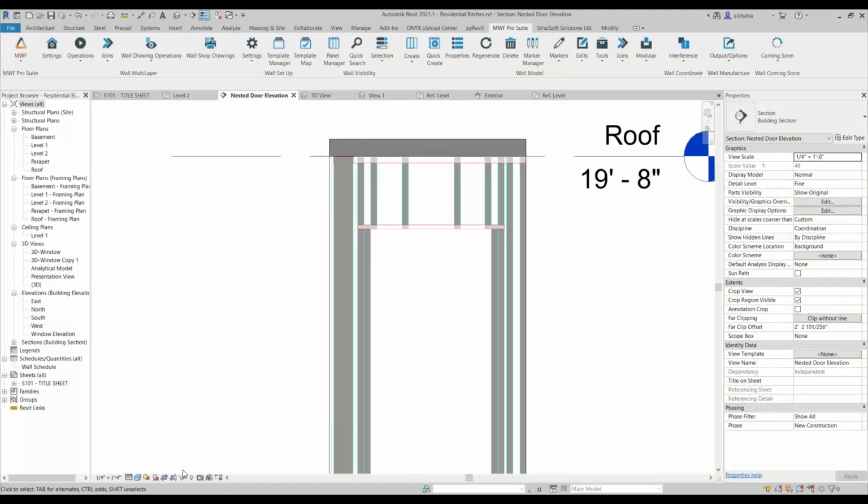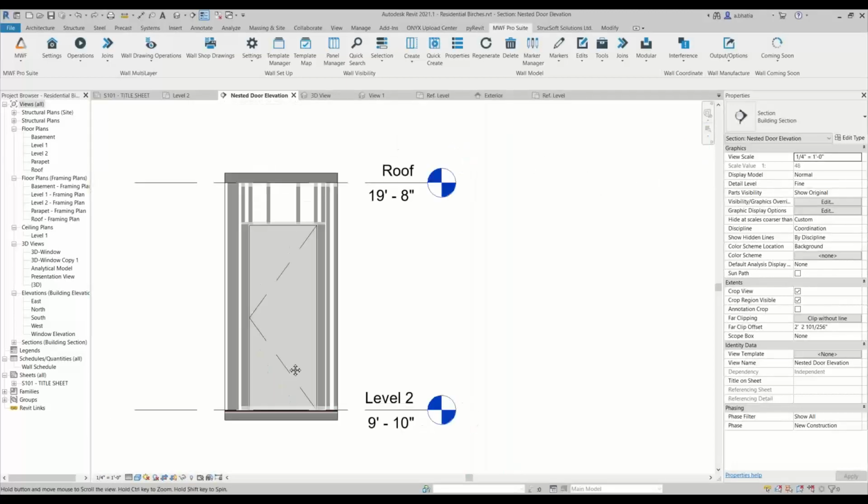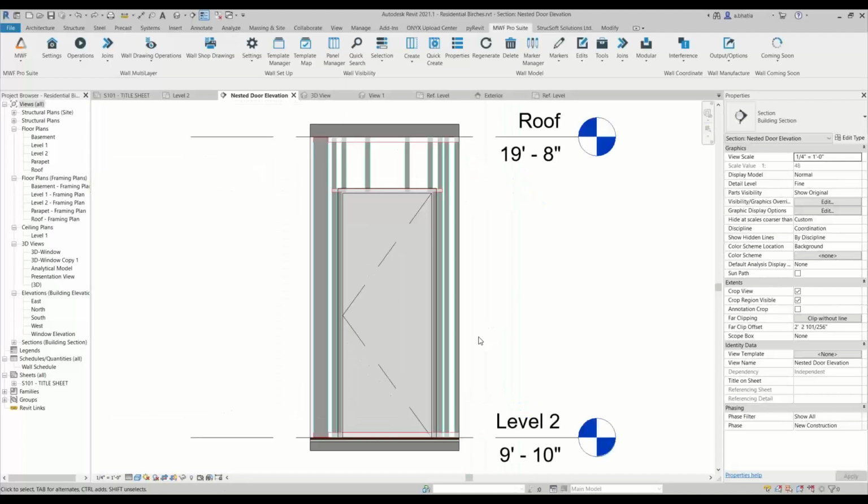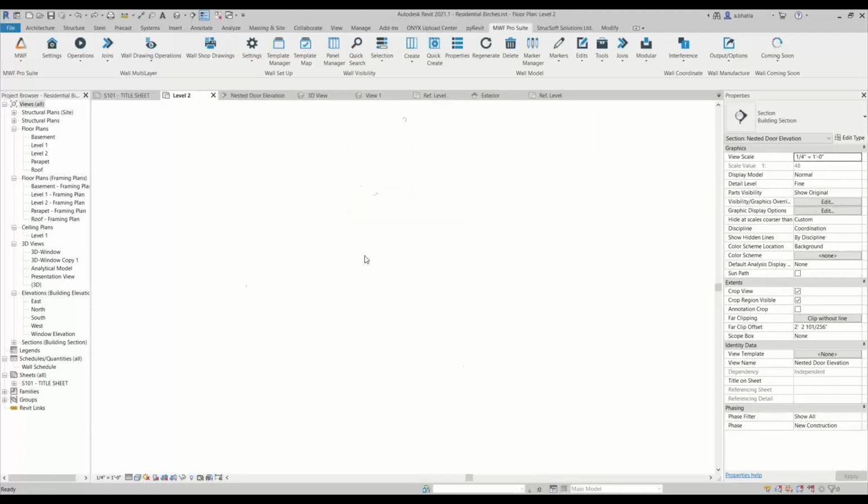So I'm going to unhide the door here this way, and I'll say ZA. Another tidbit of information I wanted to give you was, since we modified the family, every wall that has that family attached to it needs to be regenerated. So if you have created panels for every wall in your model already, and this family is maybe used like, let's check how often it's used in my project.